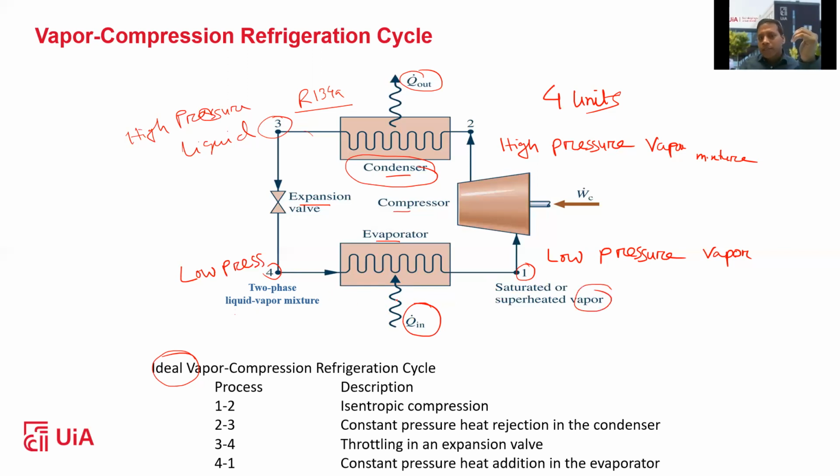So by getting that surrounding temperature, for example, if you use this refrigerant, it starts with an evaporation or saturation temperature for this evaporator. You may consider as an example 5 degrees centigrade. So when it comes to 5 degrees centigrade, it receives some heat from the surrounding.